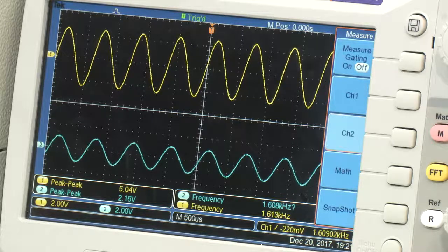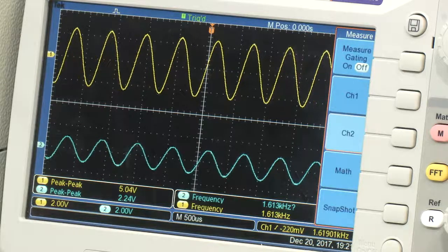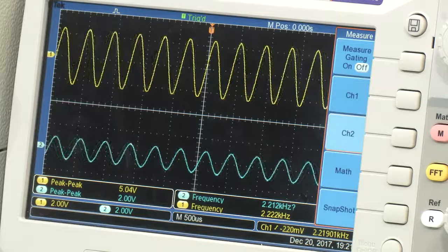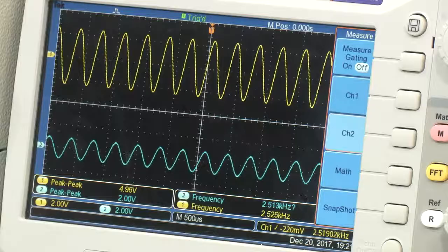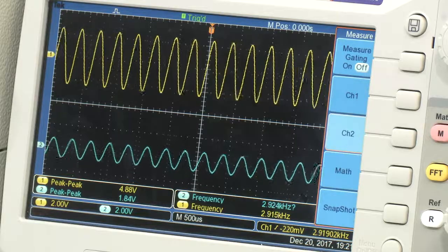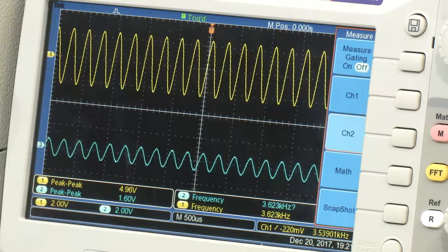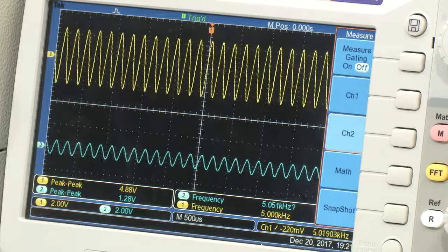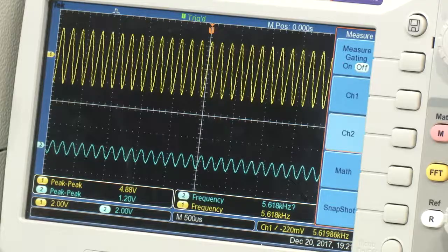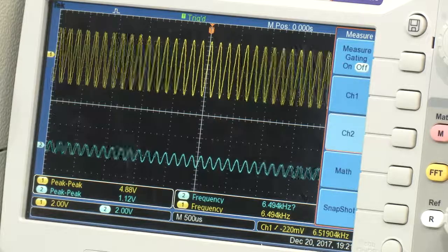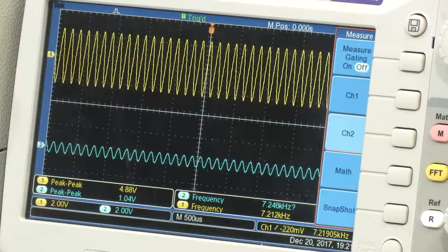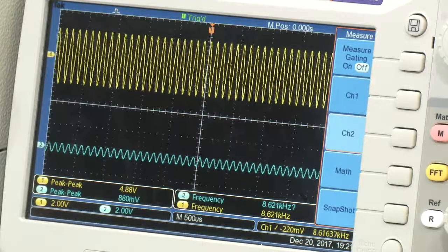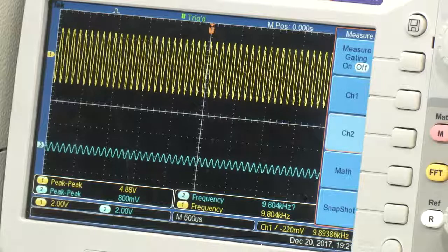So, it will only pass a certain band of frequency, but we cannot see or understand that significant difference in the output, because of the loading. We cannot delineate when the loading is there and when it is not, which band is passing and which band is not passing, because of the effect of loading. And that is why always remember, when we use a passive filter, the loading will come into the picture. So, no more passive filter, we will not use it.